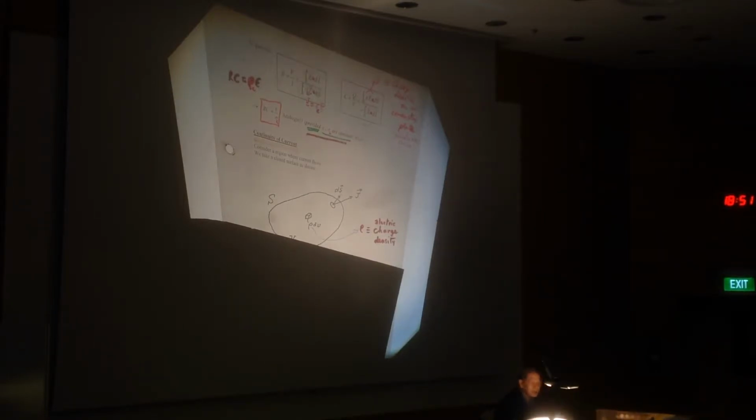Yeah. There's another relationship again, when we introduce the concept of inductance, L, C, mu, epsilon. I haven't done it yet. You will see this kind of relationship exists. The product of inductance per unit length times capacitance per unit length is the product of the properties of the medium, which is mu, proportional to L, and epsilon.